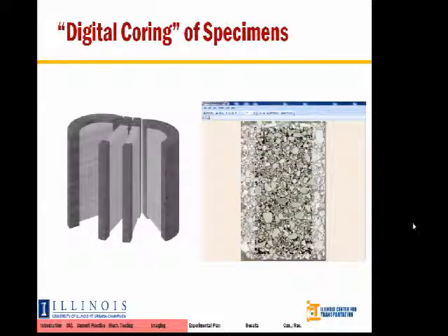We have to treat the images similarly. So what I ended up referring to as digital coring of those images. Okay? There was no sense in actually cutting and coring the imaging specimens before vertically slicing them. So in this case, the entire gyratory specimen was cut, as seen in the previous photos. If you fan it open, again, look at the relative dimensions of the cut and cored or the mechanical testing specimen relative to the 150 millimeter gyratory. We can see we need to actually digitally core the image or crop it to match the cross section at each of those slices.